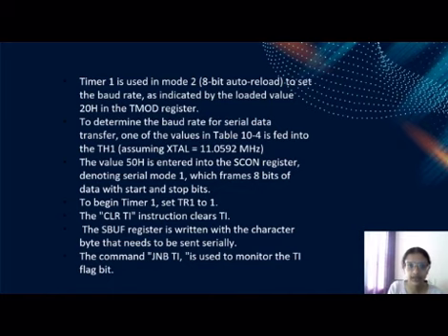Data to be sent serially is written into the SBUF register. The TI flag bit is monitored using the JNB TI command. The procedure ensures proper setup and transmission of serial data using Timer 1 and the SCON register configurations.